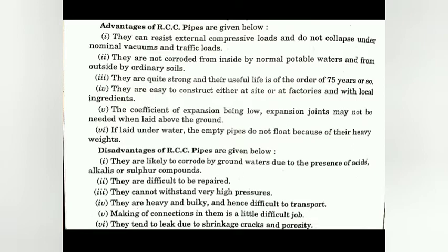Third one, they cannot withstand very high pressures. When a high pressure of water is given, there is a chance of leakage and they cannot withstand that kind of pressure. They are heavy and bulky and hence difficult to transport, and installation of the pipes is also quite difficult, and making connections in them is a little difficult job because handling them and moving them itself is very difficult because of their heavy weight. So connection, transportation, joining, all these factors are quite difficult in case of RCC pipes.